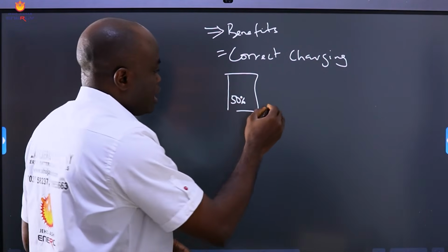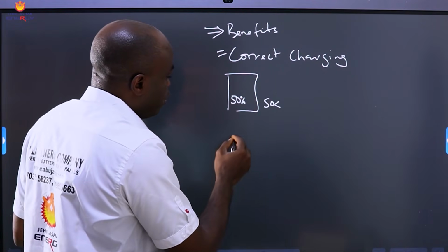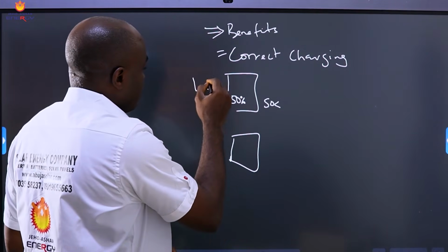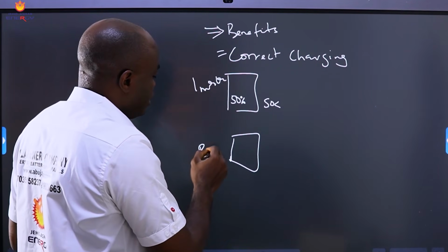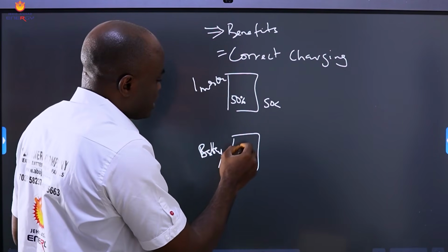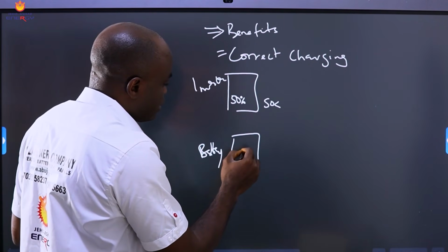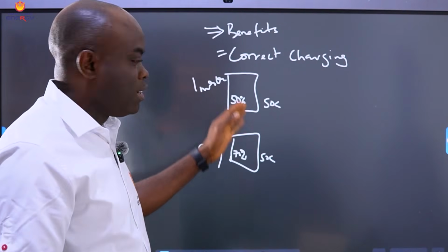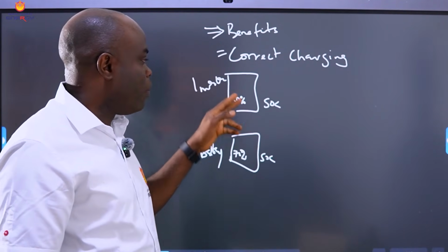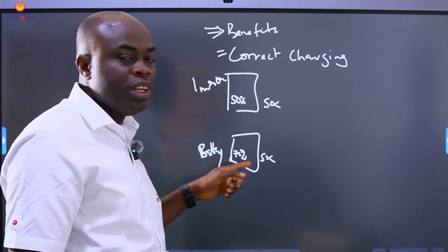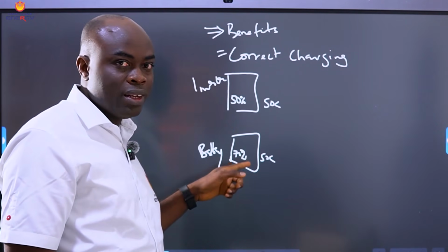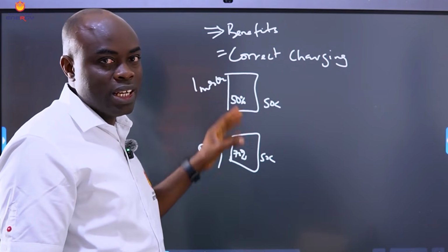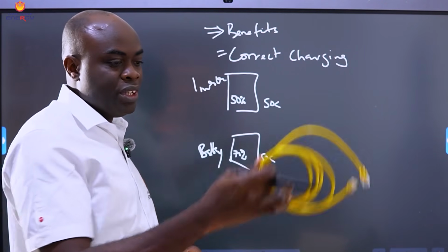That is the state of charge, SOC. But on your battery display, you see that it's showing 70%. So you can see that there's a problem here. When this guy is not reading the same information as this man, it means that there's no understanding between both of them.